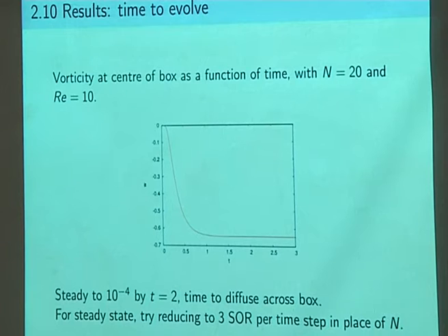As long as you don't start the Poisson solver from 0, but start it from whatever you were at the last time step. So this is a cheat's way, and it means time is no longer true time, it's some sort of pseudo relaxation time. But it's much cheaper. So if you're only interested in steady state, there's a point you could be economical and cut down by an order of magnitude the process. But you should really resolve the time variation properly. So you do need 2n squared iterations of the Poisson solver.